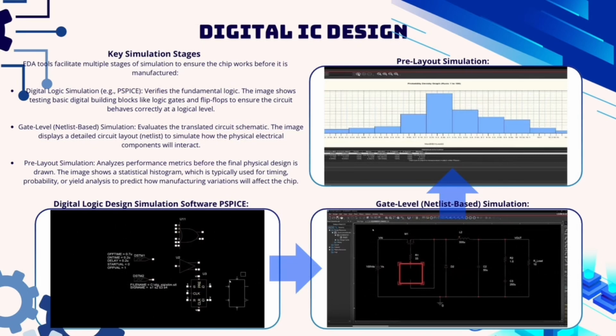Before manufacturing a chip, we have to test it virtually. That's where EDA tools come in. We run three main simulations. First, logic simulation, using tools like PSpice to verify basic gates and flip-flops. Second, gate level simulation, which checks the actual circuit netlist to see how components interact electrically. And third, pre-layout simulation, which uses statistical analysis to predict how manufacturing variations might affect performance, kind of like a stress test before a chip is even drawn.